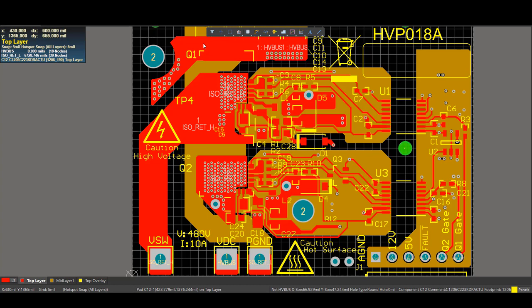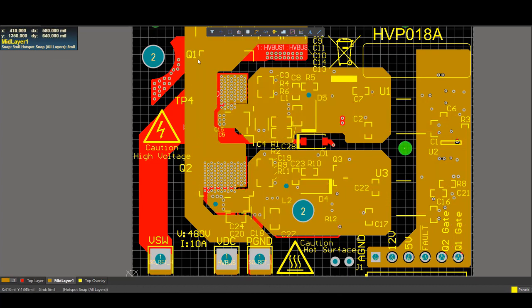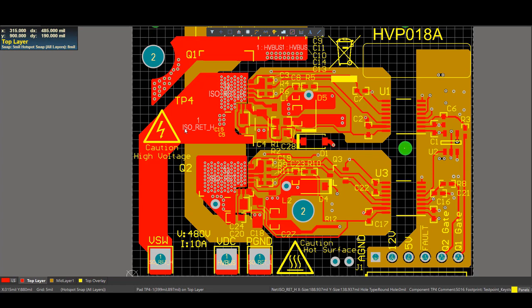Now, let's turn our attention to a good layout, which follows the design guidelines we mentioned in the slides, and fixes all the commonly made mistakes in the previous layout. This layout is from our LMG3410R050, which you could find on the ti.com/GaN website. First, looking at the power loop, we have the power going from the top, and then the return trace is directly underneath, which maximizes the inductance cancellation. Looking at the overlap between the switch node and the ground trace, the total area is minimal.